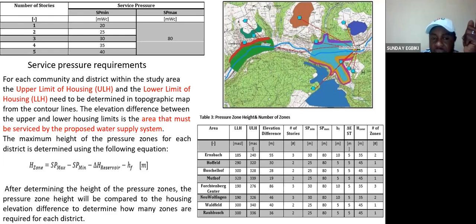You will know that beforehand, either 4 meters or 5 meters. And you will calculate your frictional head loss, HF. In a consumer tap, in the municipal water distribution, the frictional head loss is 10-meter water column. After that, you will calculate the number of zones.